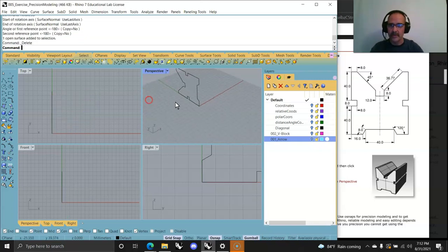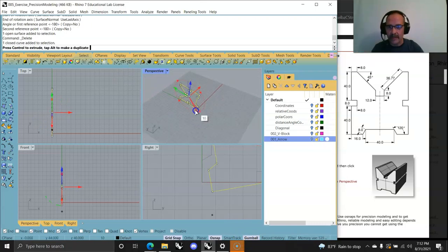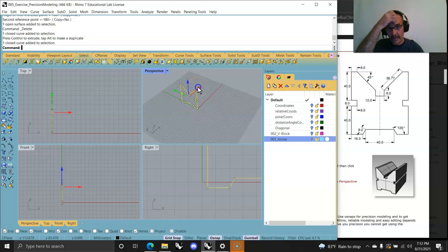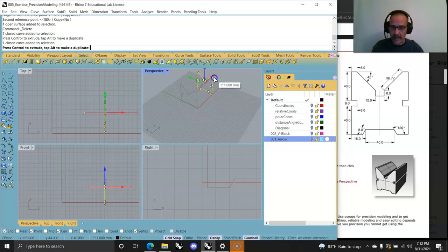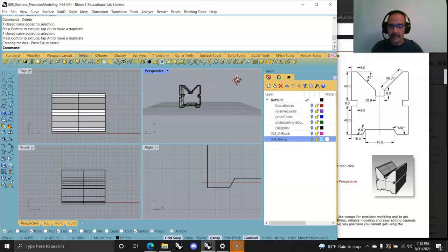point I'll take this one, and it might be nice to grab the gumball, this object, but because I'm not rotating it from center, it probably wouldn't matter if I did. I could roll it, hold shift, and get it to set there. Now I can grab this object, and there's shortcuts: dragging this arrow, hitting Control, tapping Alt, you've now extruded it in this direction. And at that point, you have 2 planar ends.